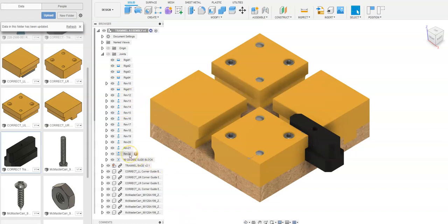I don't need to know all these revolute constraints, but you can see, we put a revolute constraint even for this dowel pin right here. If I wanted to go through and name every one of these joints, it would make it a lot easier for me to itemize exactly which one each one is. The next one we'll call it a 90-degree arched slide block, or we'll call it the arched slide block or something like that.